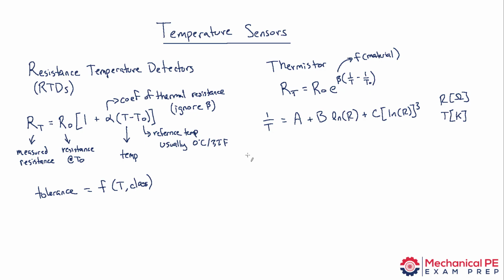And the third and final type of temperature sensing device is the thermocouple. And the fundamental operating principle for the thermocouple is that it's comprised of two dissimilar metals that are run in parallel in an insulated cable. And there's a temperature difference across what's called the reference junction and the end of the thermocouple where you're interested in finding the temperature. So for example, let's draw our two cables in parallel. These would be put in the same insulator, but they're never in contact except at the very beginning. So these would be joined into a single node, and we call that the reference junction. And we know the temperature at the reference junction, T sub 0. And then on the other end of the cable, the temperature is being measured. Let's call that temperature T.